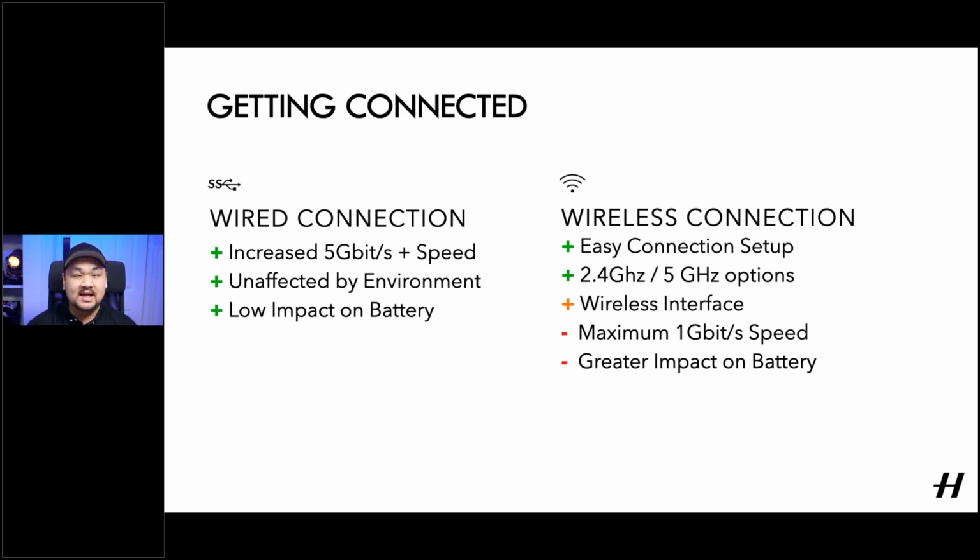But you do want to keep in mind that typically cables you'll see for a Type-C to Type-C connection max out at around 15 feet or 4.5 meters. If you're using one of the adapted cables, so the Lightning to Type-C, these typically will be a 1 or 2 meter option at best. And typically for most cables after a certain distance, you start experiencing line loss or the data connection starts to get inconsistent. And likewise, it is a physical interface, so it is a cable that can be tripped over. So do be mindful of the setup when you have cables around you.